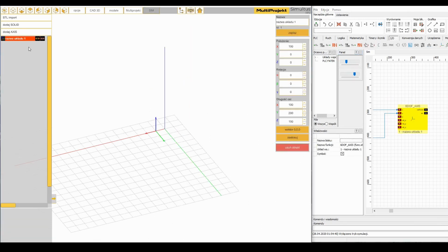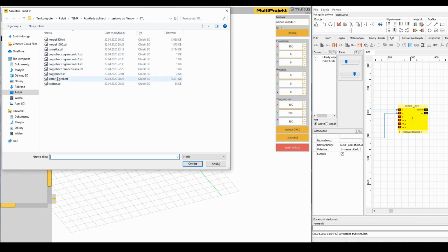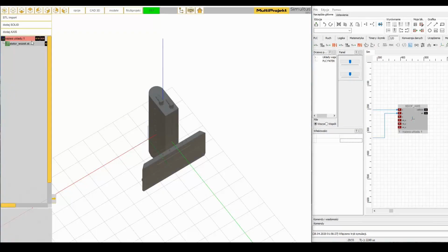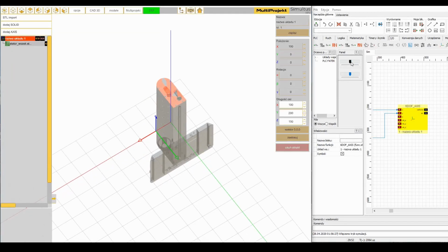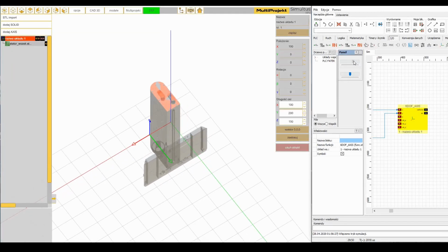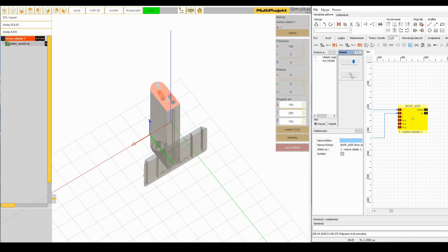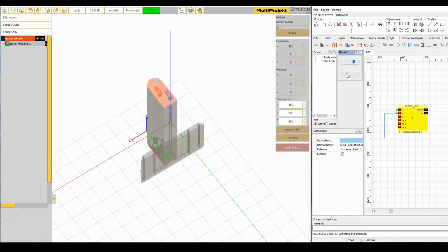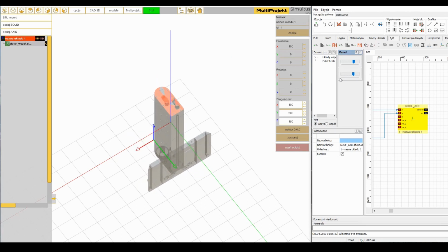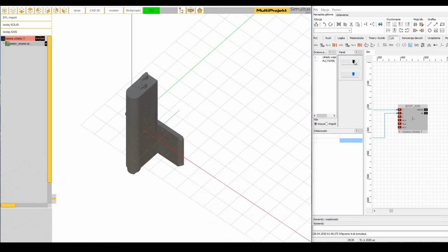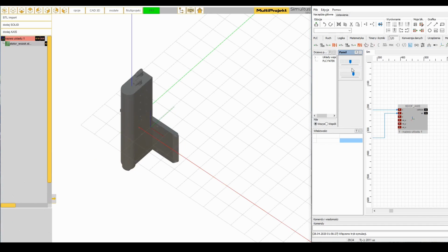Let's connect a 3D solid to the coordinate system. By moving the coordinate system, we move this solid. In the control systems that we will build, the position set in the block properties will be the starting position. The position set through the 6DOF axis function block will be the position from the control system.